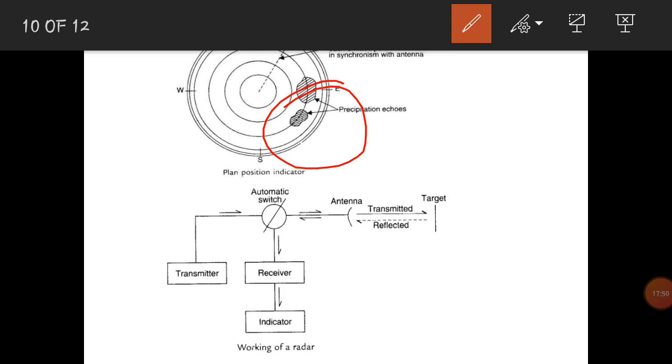Unfortunately, radar does not measure rainfall rate directly, but rather the backscattered energy from precipitation particles in an elevated volume, and is prone to errors. Errors come from variations in the relationship between the backscattered energy and rainfall rate, change in the precipitation before reaching the ground, and anomalous propagation of the beam.